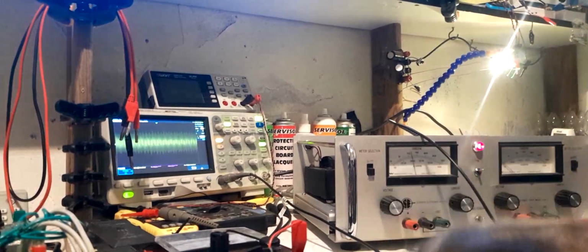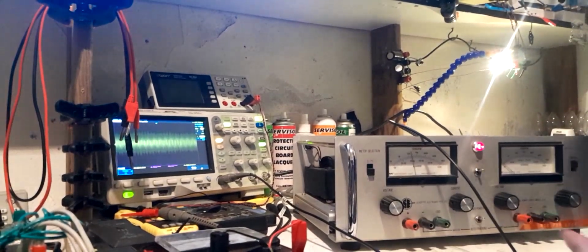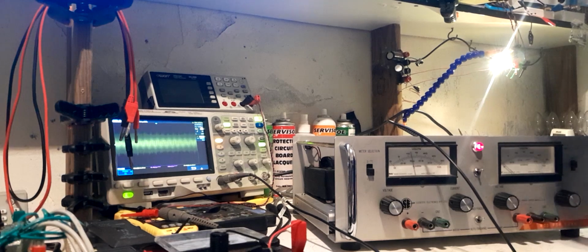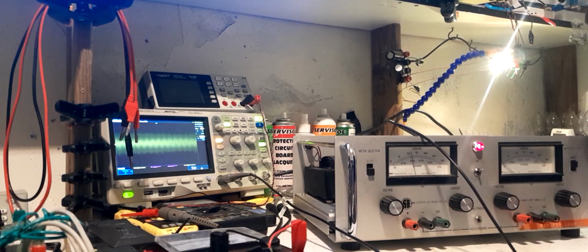But man, I just dropped my shorting bar, if you can call it that. It's a bit of solder wick. That's either remnants of high frequency oscillation getting fed through, but I think that's Zener noise. I'm not even too worried about that. It looks exactly the same as what the reference did when it was unloaded. So I think that is coming from somewhere else.